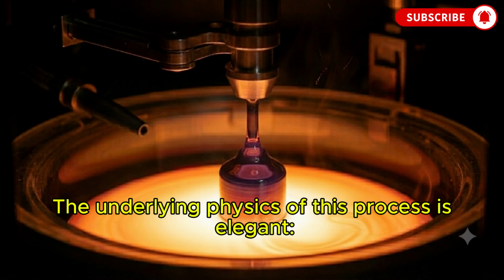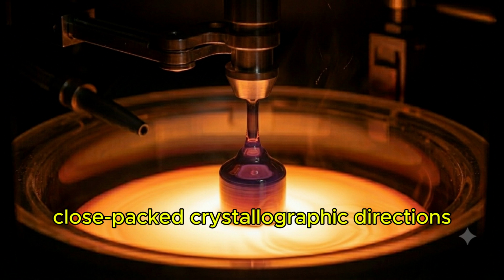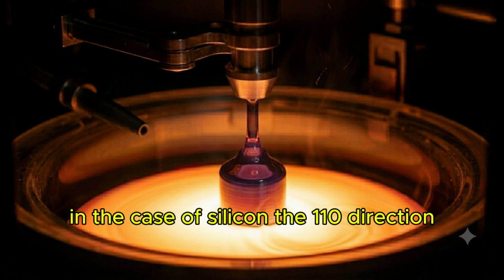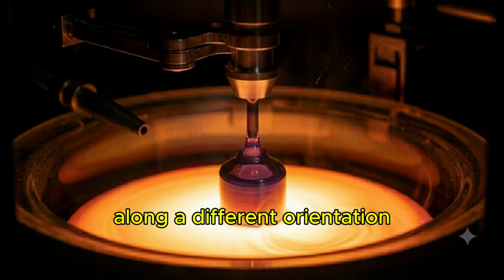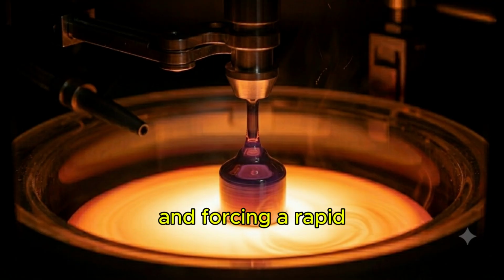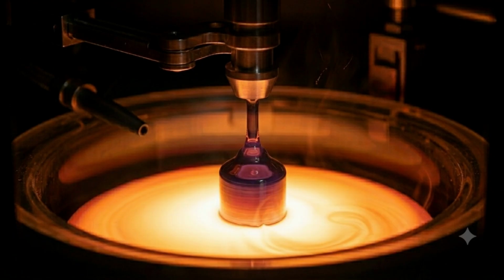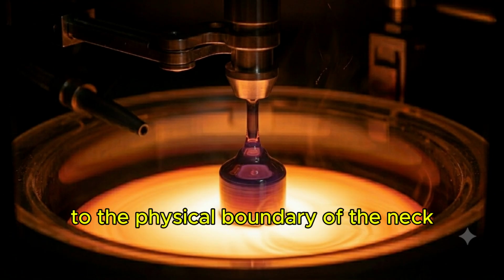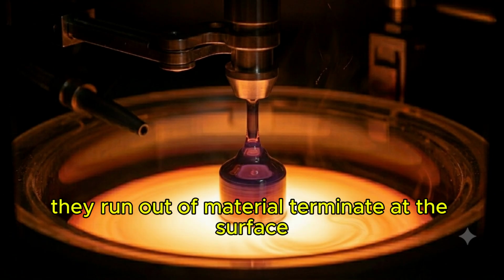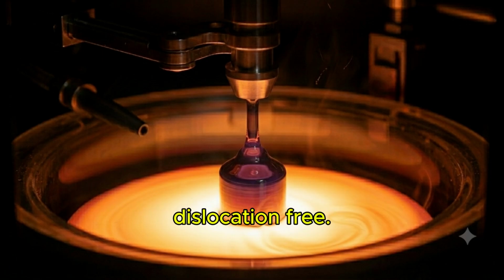The underlying physics of this process is elegant. Dislocations prefer to propagate along specific close-packed crystallographic directions, in the case of silicon, the 110 direction. By intentionally growing the crystal along a different orientation, like 100, and forcing a rapid, narrow vertical growth rate that exceeds the climbing rate of the dislocations, these line defects are literally forced to grow outwards to the physical boundary of the neck. They run out of material, terminate at the surface, and leave the core crystal matrix completely dislocation-free.